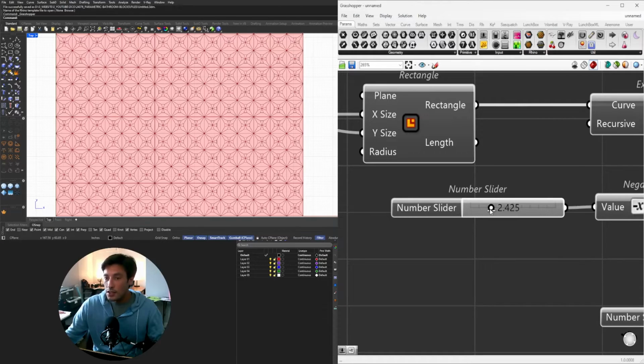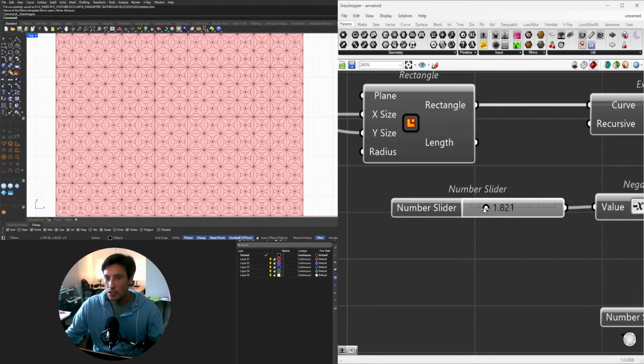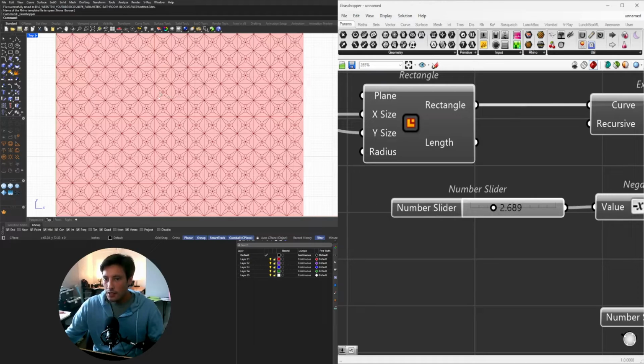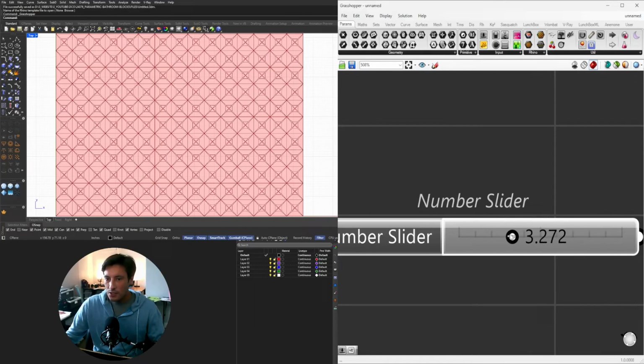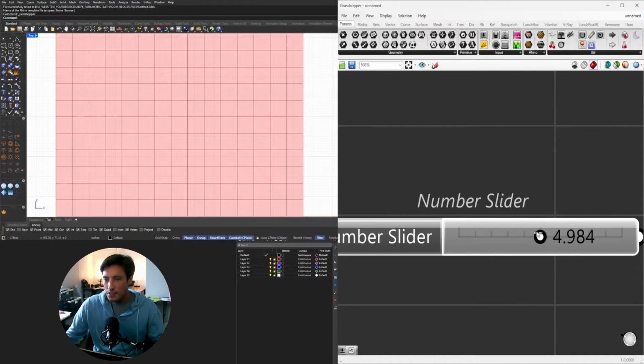Now this is just here using the offset. So notice that this line segment that we offset and shortened, that is what we're working with here. So let's say 3. Then the shortening of it. So this actually expands it out. So there goes too far.